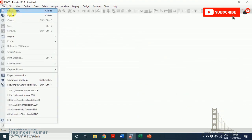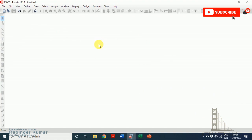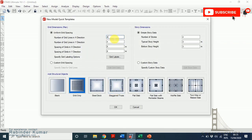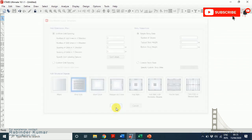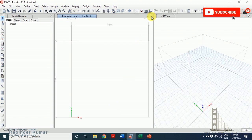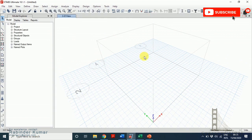So first let me click on new model. I will select the metric SI system. As the length of the beam is 5 meters, I just need two grid lines in the X and Y direction, 5 meters, 5 meters. These things are optional. Click OK. I don't want the plan view, so we will work in the 3D view.